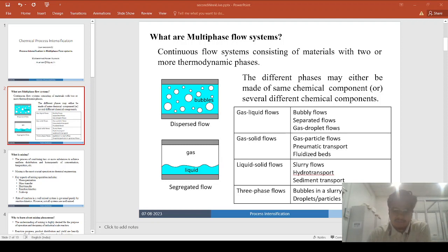The performance of the reactive distillation is influenced by the size and location of the reactive and non-reactive column sections. Not only that, the reflux ratio, feed location or throughput also plays a very important role in the performance of the reactive distillation unit.